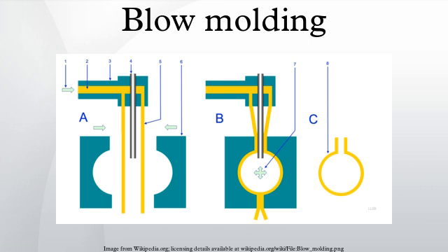Different types of the materials have their own physical characteristics affecting trimming. For example, moldings produced from amorphous materials are much more difficult to trim than crystalline materials. Titanium-coated blades are often used rather than standard steel to increase life by a factor of 30 times. Injection blow molding. The process of injection blow molding is used for the production of hollow glass and plastic objects in large quantities.